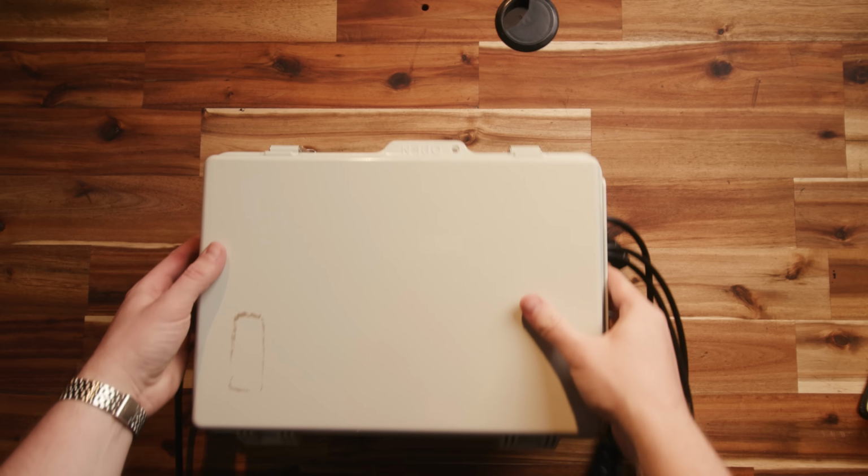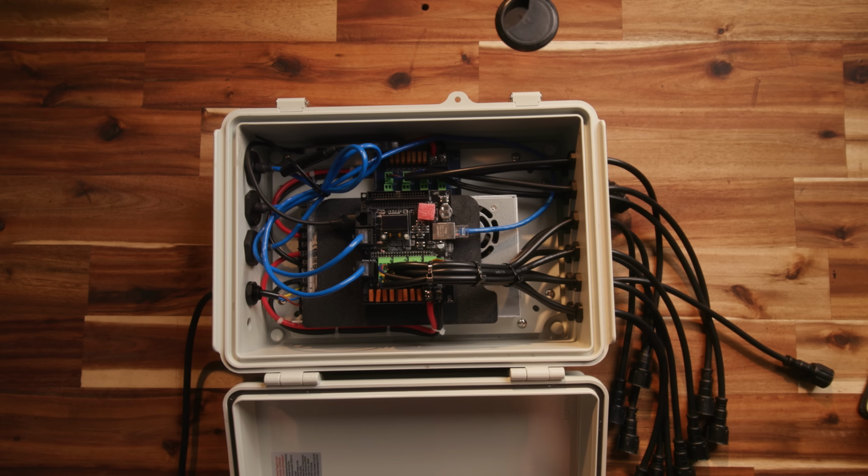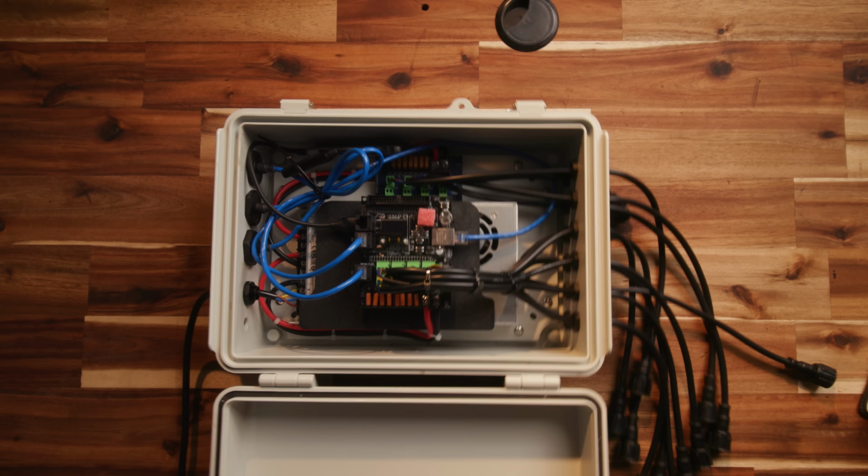This calculator also let me calculate the power required for the entire tree. In my case, I'll need about 900 watts of power to drive the whole thing. I'll also require quite a few pixel ports to manage this tree. The controllers I'm using can drive 800 pixels per port, so we'll need to split it up over a bunch of ports. I'll show you a bit about the controller in the installation video a little closer to Christmas. For now, we need to get our tree built.